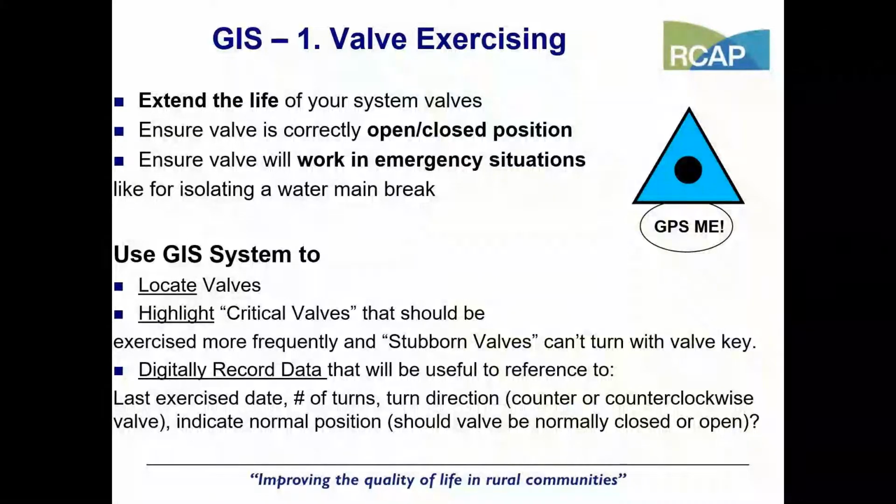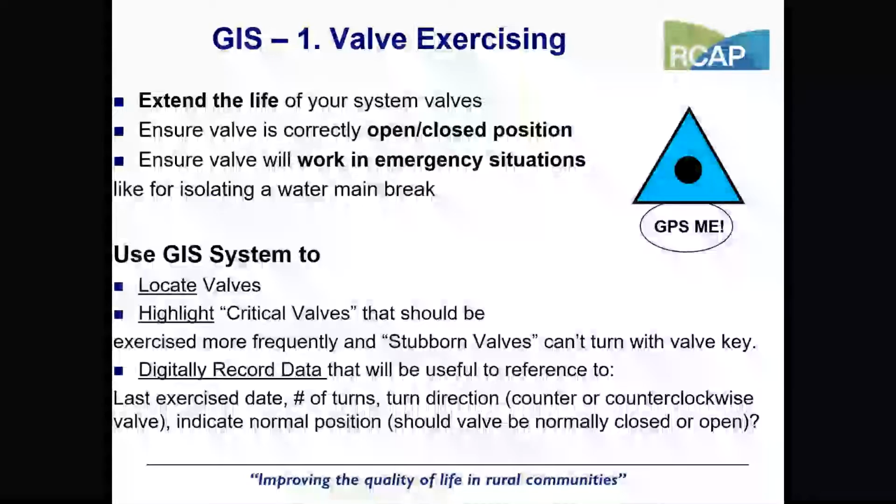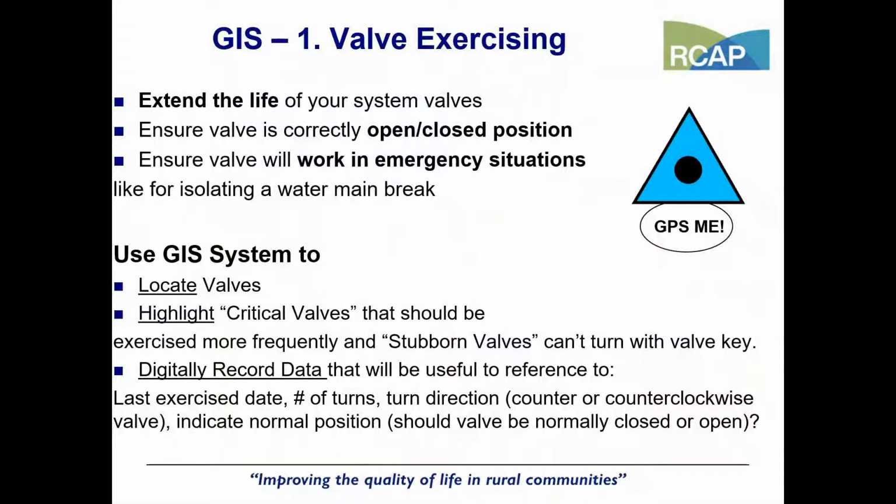Yeah, so since a lot of you are valve exercising, this will be very useful to add to your GIS or create a GIS system to record this operation. So, of course, exercising your valves, you're going to extend the life of that valve. I know a lot of systems, once they go so many years, they're very afraid of actually